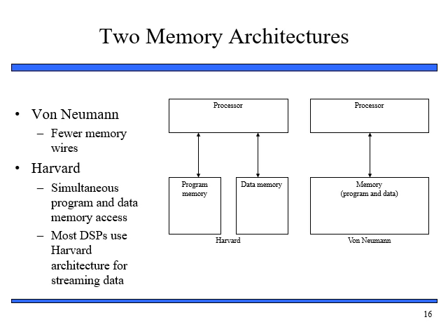Memory can be on chip or off chip. The processor accesses on-chip memory faster, in one cycle, compared to off-chip memory. However, we are limited in the capacity of memory on chip, so we need to go off chip. Still, whenever we have memory on chip, the processor will access it faster compared to off-chip memory. So that was about the two memory architectures. Let's move on to the next slide.